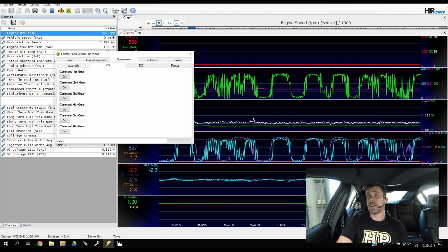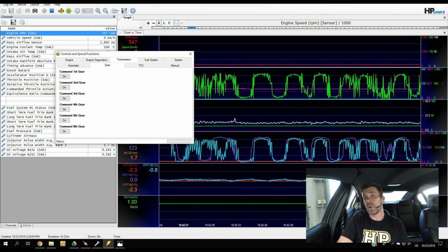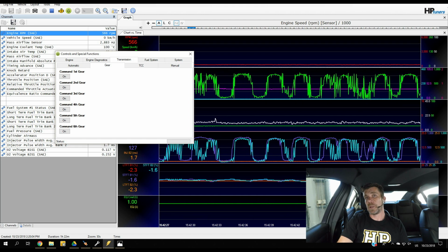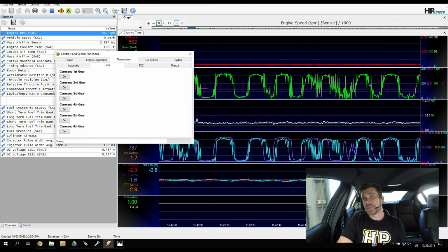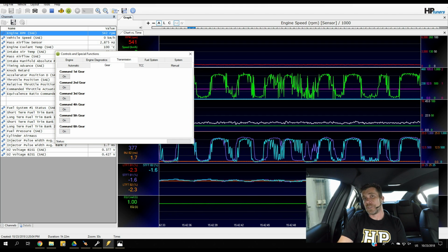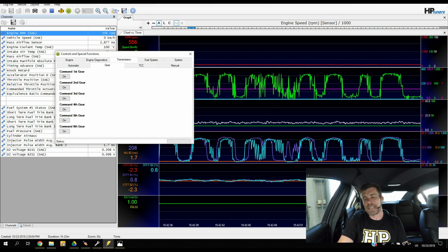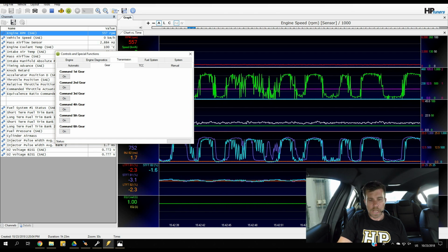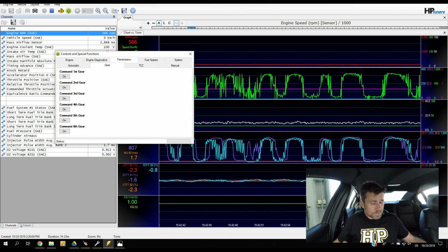It takes a little bit of testing to find out exactly what points you can do this, but then you can be pretty consistent. And the difference between 80% throttle and 100% throttle down in that low 800 to 1000 RPM of the rev range really doesn't have a huge impact on your tuning. So a little tip for you there.